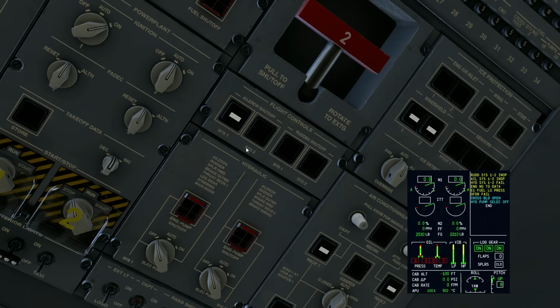There's a bunch of valves in the wings and in the stab that will not send fluid to system 1 for the ailerons themselves. And then same with the rudder. The rudder has a 2-system hydraulic. Two systems feed the hydraulics for the rudder. And so, for example, system 1 is not needed above 130 knots because we have a very, very big segmented rudder. This thing looks like a barn door.